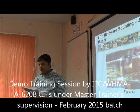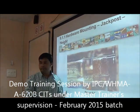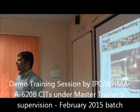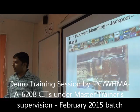Height is adjusted by adding or removing washers. So if you want to attain 0.5 mm, we may have the spring washers, we have the plain washers. To attain that height, we can install or else we can remove the washers accordingly.